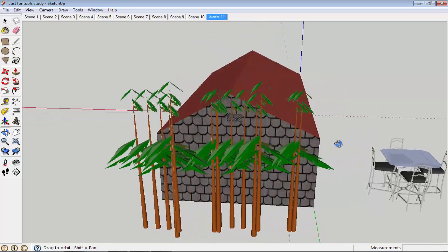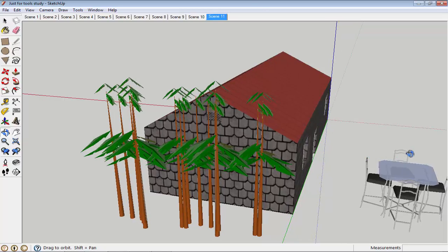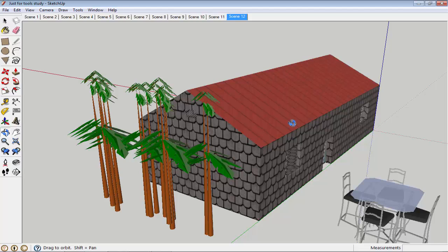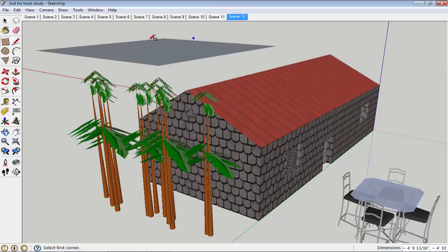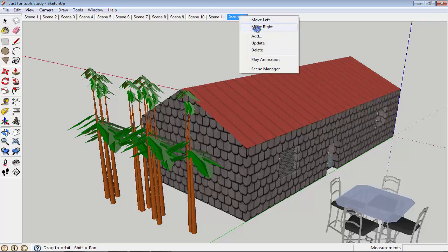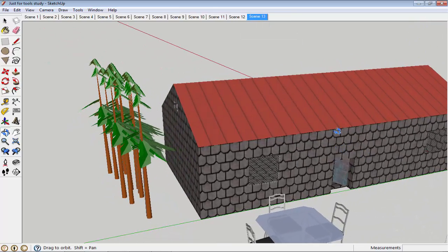Again add. Okay, again I will click. It is actually the scene, meaning when you move your drawing, when you zoom out, zoom in, it will be recorded, not your tools. For example, if you draw these things, it will not record. It will only record your zooming and your movement. Okay, that's it. So again I will move this and I will click on add scene, add.